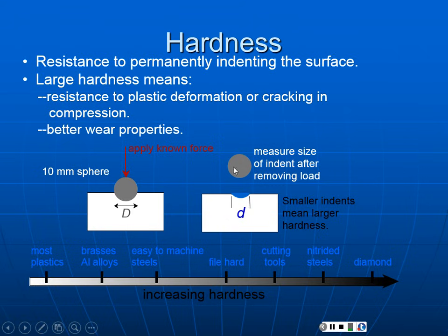Now the key here is this quantity, the hardness, however you measure it, is very closely related to yield strength and ultimate tensile strength. And so we'll often use hardness as a substitute or a proxy when we want to measure yield strength and we can't make a tensile bar, we want to measure ultimate strength and we don't have anything we can break. We'll measure the hardness, and because they're closely related, we can estimate one from the other. And in fact, your conversion chart you've used in lab, if you're paying attention, when you converted from C scale to A scale, there's a far right-hand column which is tensile strength. And that is the approximate ultimate tensile strength of a material that has that hardness, at least a ferrous material that has that hardness.